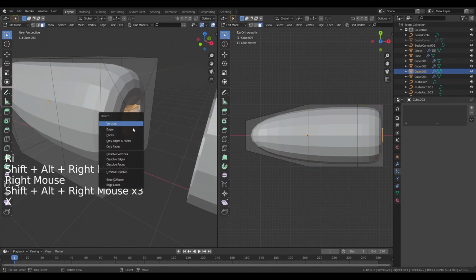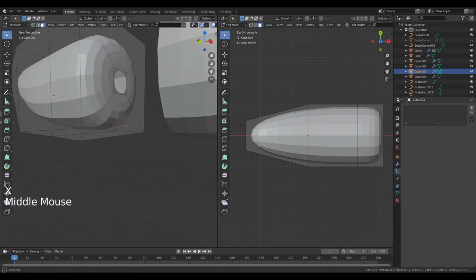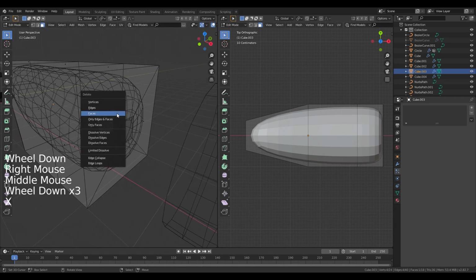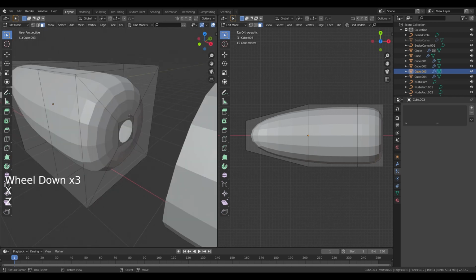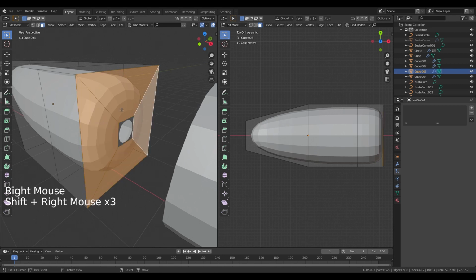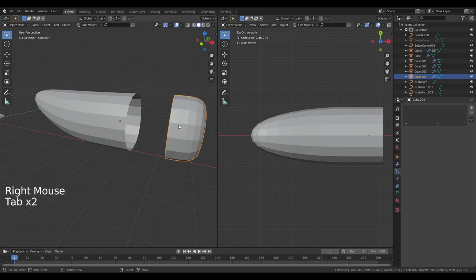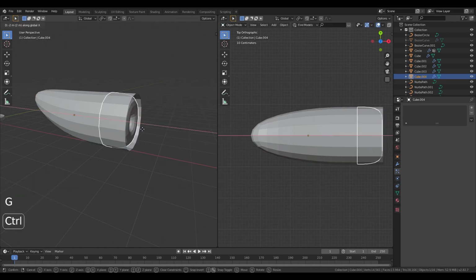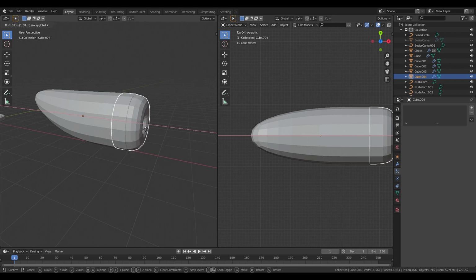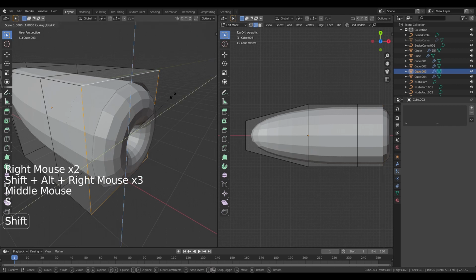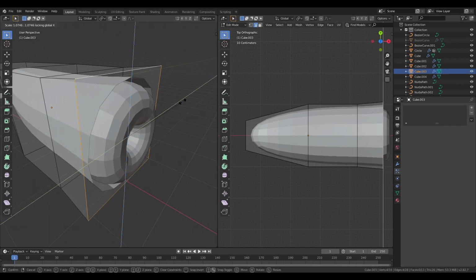I'm going to also check through wireframe. I'm going to delete this face that's inside because we don't need it. And I'm perhaps going to delete also the front faces. So we have this. I'm going to select the engine again and move it back by 2 increments, maybe even less, let's say about here. Select the body again. Now we can select the edges, just the edges, S, X, and scale them down so they fit inside the actual engine, like so.